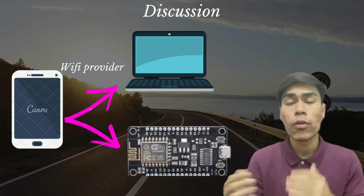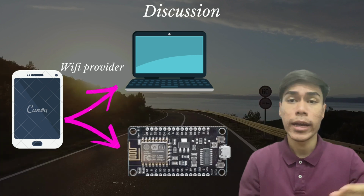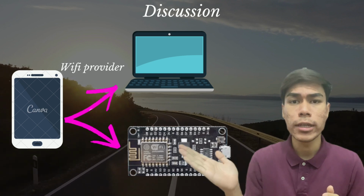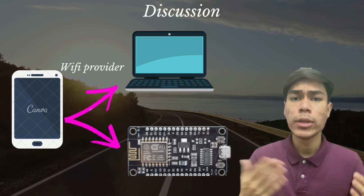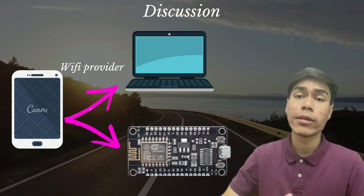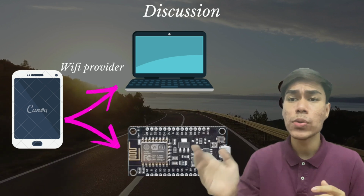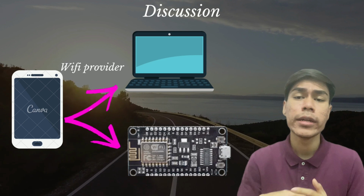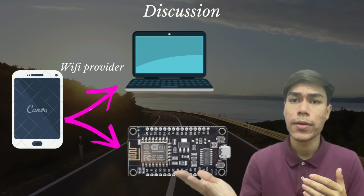I can see from the result that the NodeMCU can detect human presence using the program that I executed. We can see the differences between the 2 feet and 4 feet lengths from the distances I have measured. When the distance between the NodeMCU and the phone is increased, the RSSI reading will rise. However, if a person walks between the NodeMCU and the phone, the reading will increase, since RSSI can identify human presence even if there are other people there.